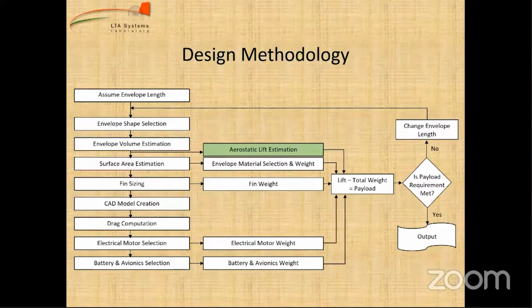But some slides back, I had told that there is one thing called net lift and another thing called gross lift. So how will you calculate gross lift? What other density do you know except the gas? Air density, rho A, ambient air. Correct.